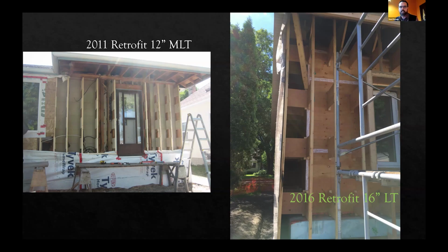The image on the right is how we do our retrofits now, 16 inches, but you can also see that there's a solid sheet of plywood in behind there. And on my retrofit, you can see the old gypsum lath that's the inside wall. So I was relying on the airtight drywall approach for airtightness, which I wouldn't really recommend. And now we try to use that taped plywood system that ensures airtightness. That's the key. You have control over your airtightness. So that's my chief learnings from this.